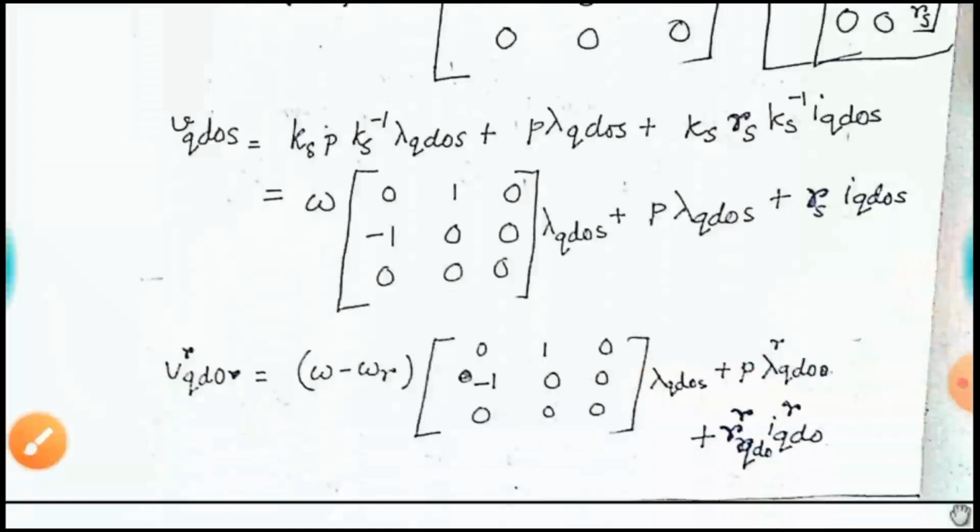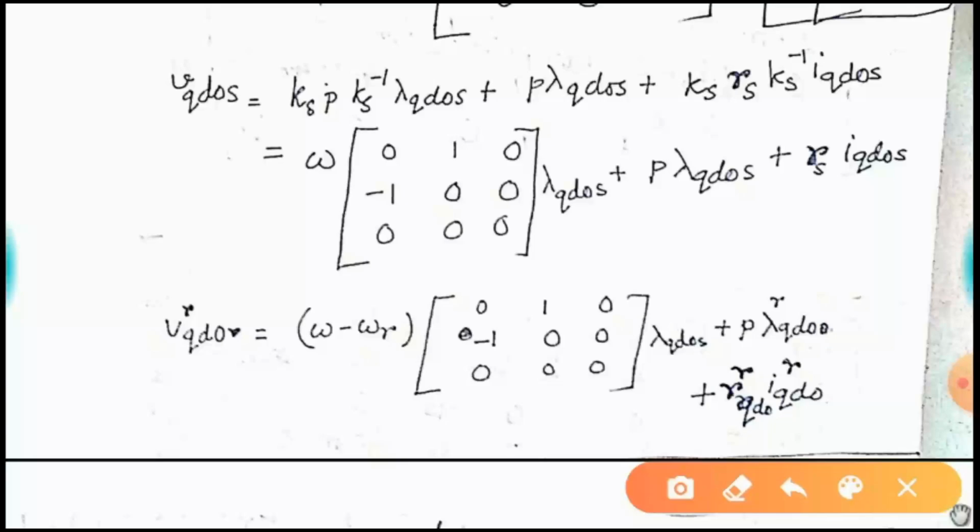But when we are dealing with the rotor quantity, the rotor is not standstill. Do remember that I have reminded you several times that this is the sole reason that allows us to draw phasors of apparently two different frequency signals on the same graph.